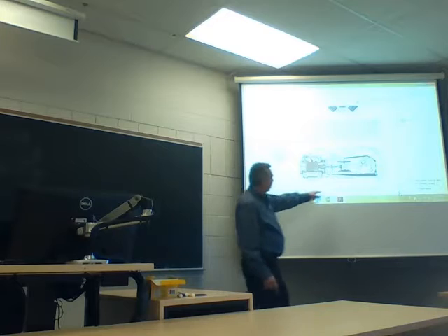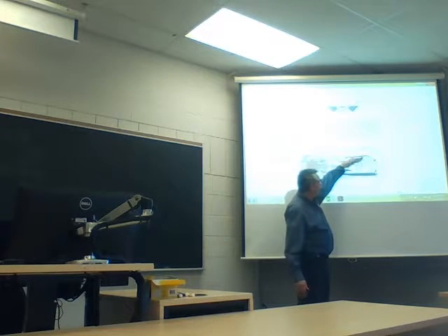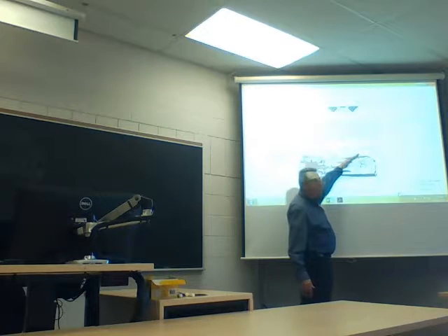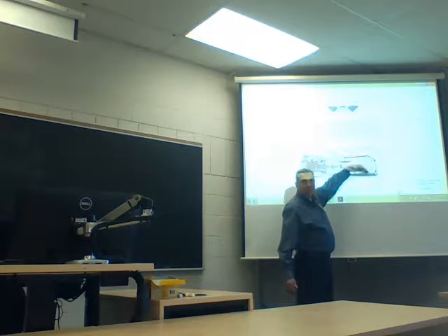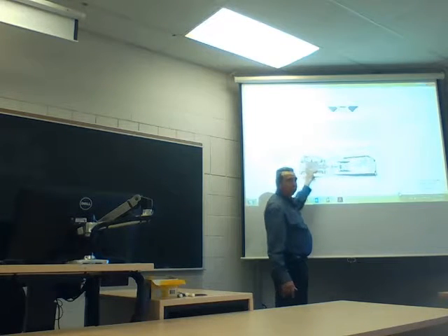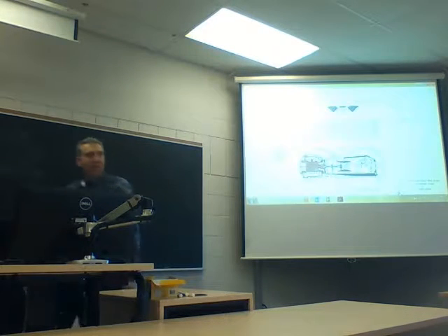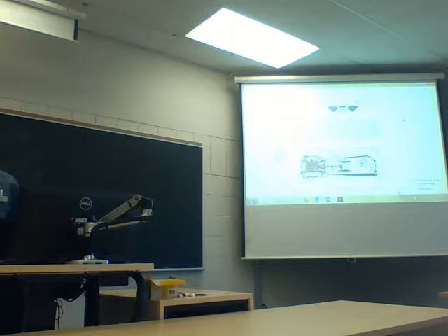See right here? The crosshead right here. You see how this crank can actually move as this goes around and moves? You can never seal that because it's slopping back and forth. If you hold it still, we can actually seal it. That's why we use the crosshead to go back and forth. Now we got it? Say yes.